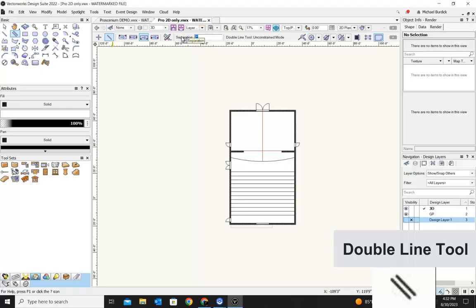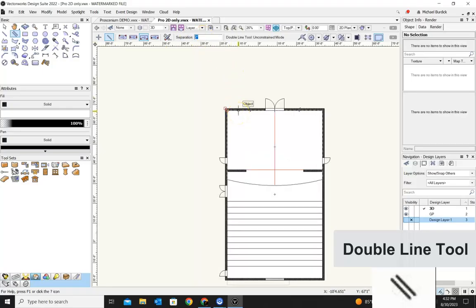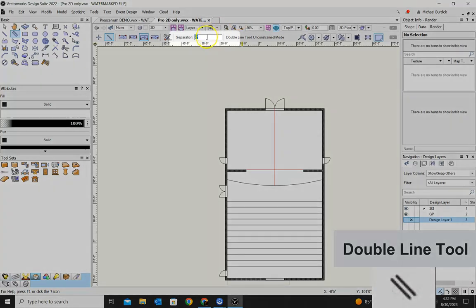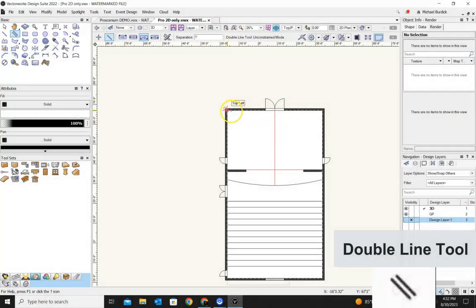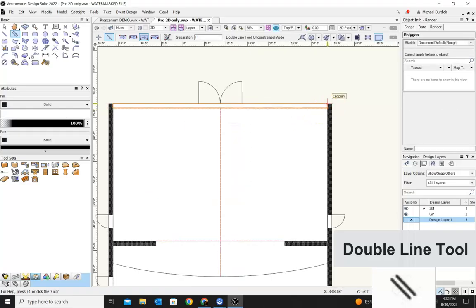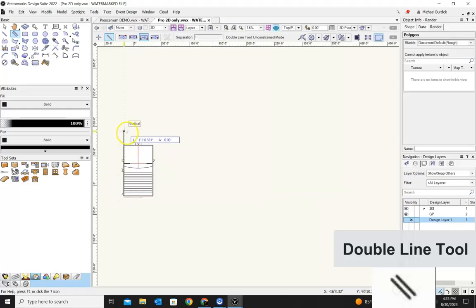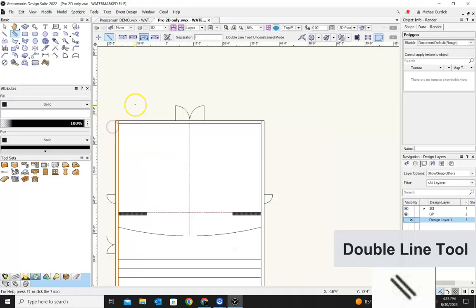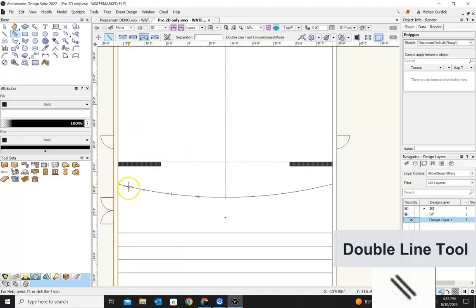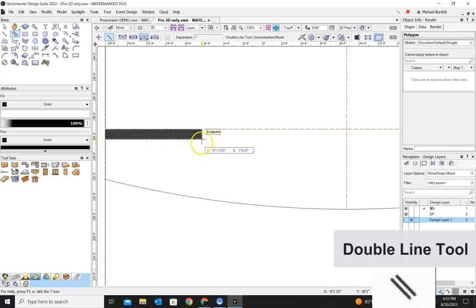And the walls on this are all 1 foot thick. So I'll change it up here, 1 foot. And I will just go ahead. I will trace. It'll snap right to where we want it to, just tracing the two-dimensional one that's underneath it. So now we've got our 4 walls. We can go ahead and add these in as well.